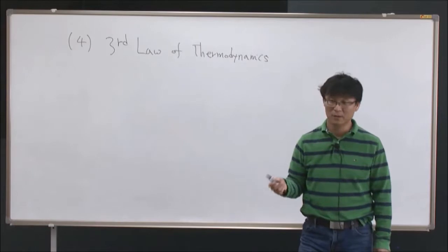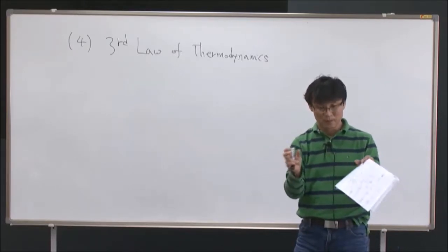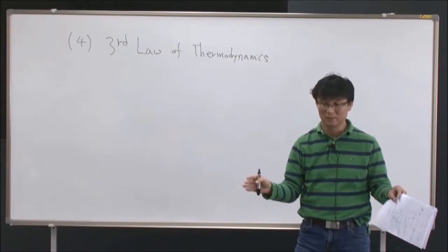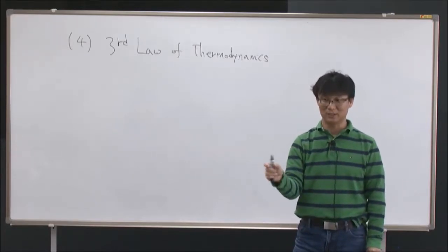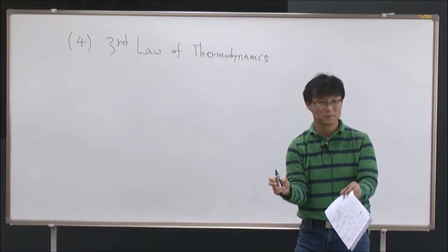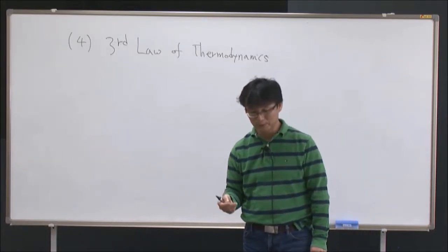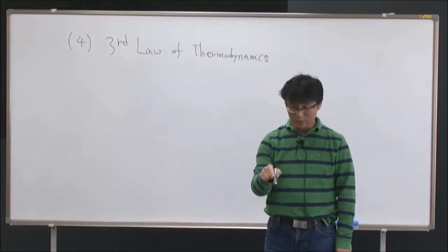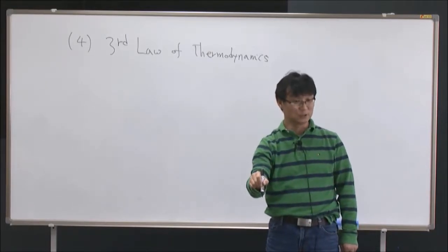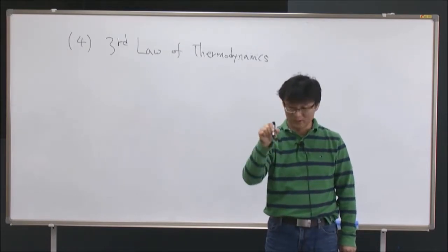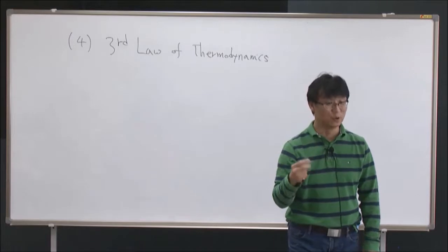So at 0 degrees Kelvin, of course between the atoms there's some repulsive or attractive force. However, if all those things are cleaned up, and we bring this material to 0 degrees Kelvin, there's no movement of the atoms at least. So they stay in exactly the same position. This is a very ordered state. For example, if I have FCC iron, I know exactly where my lattice points are, and if I click a lattice point, I can directly hit my iron atom. There's no disorderedness. I know exactly where my iron atom is in the lattice. So in thermodynamics, this means there's no disorderedness.